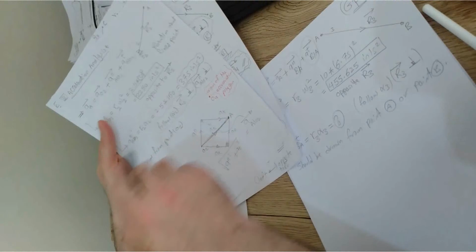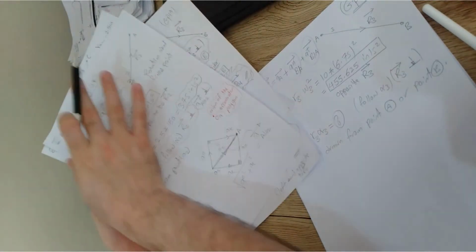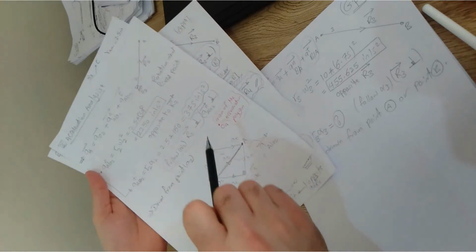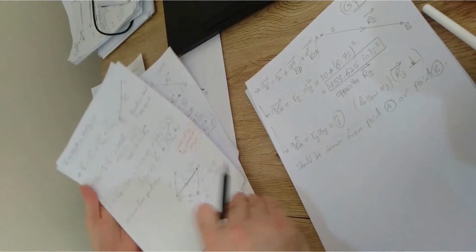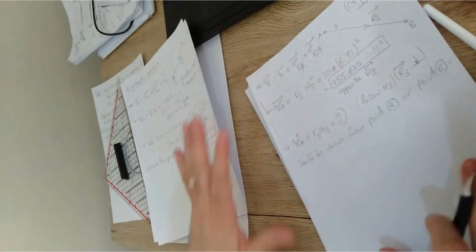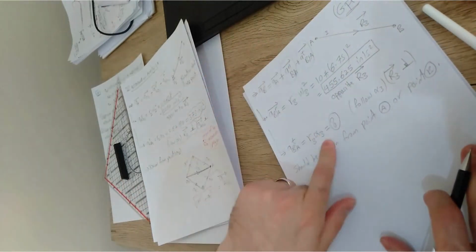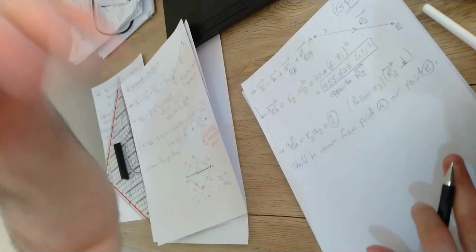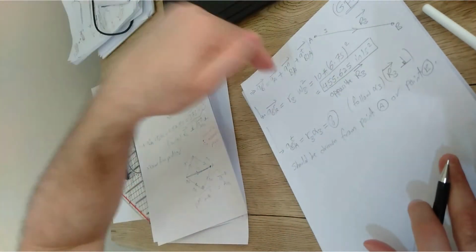We're going to define point A first, since this link is fully defined. So starting from O2, we're going to find point A, then from point A, we're going to find point B. But point B will not be found completely through this link because it has some missing data. It means that we're going to end up with one locus, but we need another locus for the same point, which is point B.